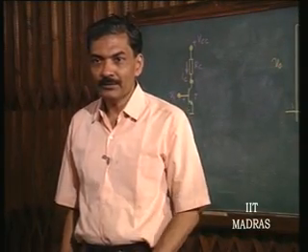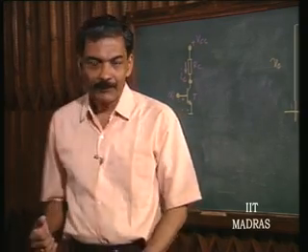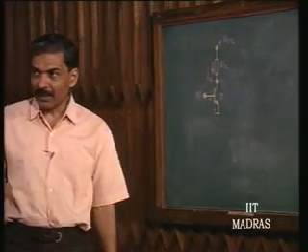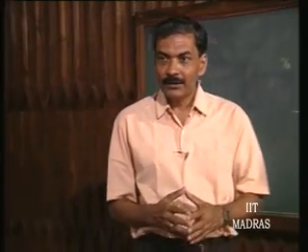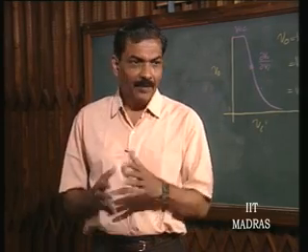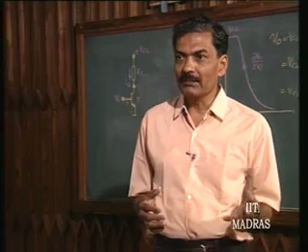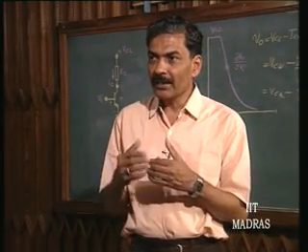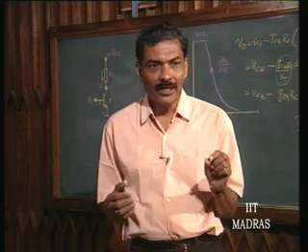So, what do I do? I use another supply. So, the dual supply concept comes, okay, if you want to get rid of coupling the whole circuit by means of a capacitor, and capacitors are things which have to be avoided in integrated circuits. They are not available, okay. Even though they are available, they are available with very small values. They have to be cautiously used.